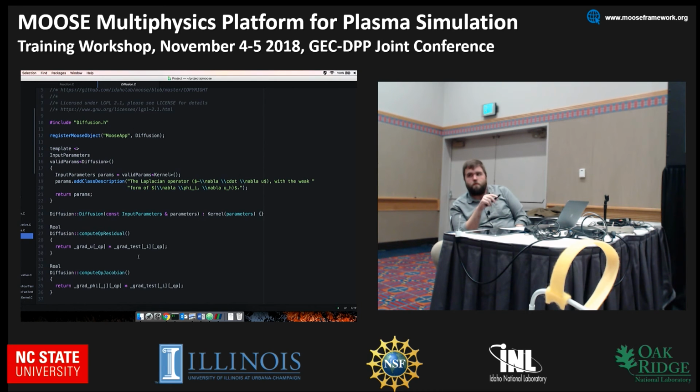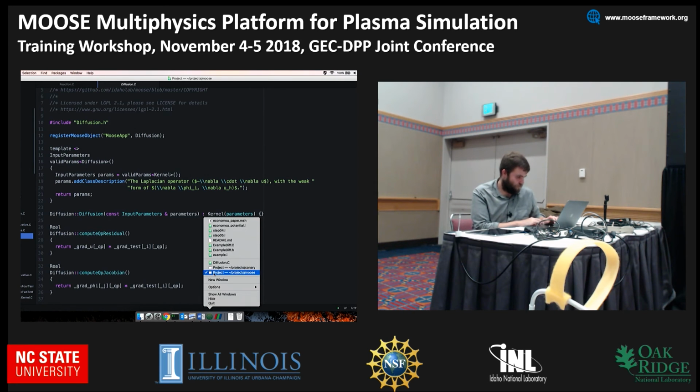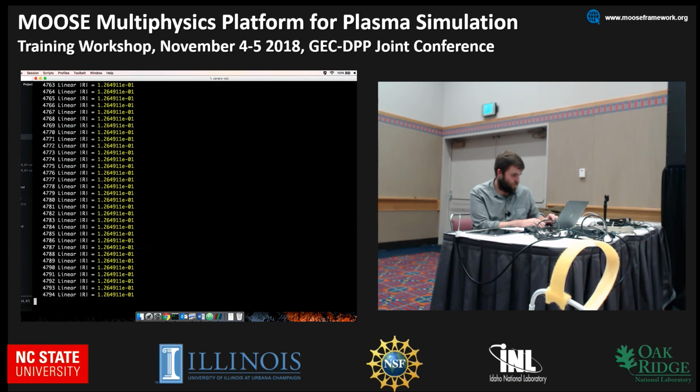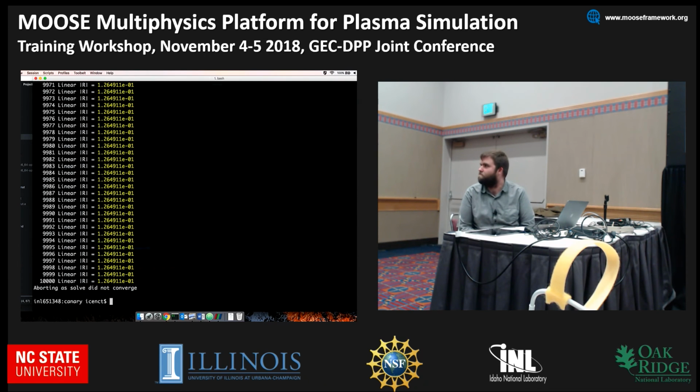Could we just once try, in your example, if you remove the reaction term? It should be ill-posed. Can you try what happens then? Sure. What happens is that we will get a solution, but it's just going to be wrong. So I'm going to comment that out. Yeah, actually, it doesn't converge. Aborting, solve did not converge. So the math is right. This is exactly what you want to have, right? Yeah. We've built a basic structure for going to the next step.